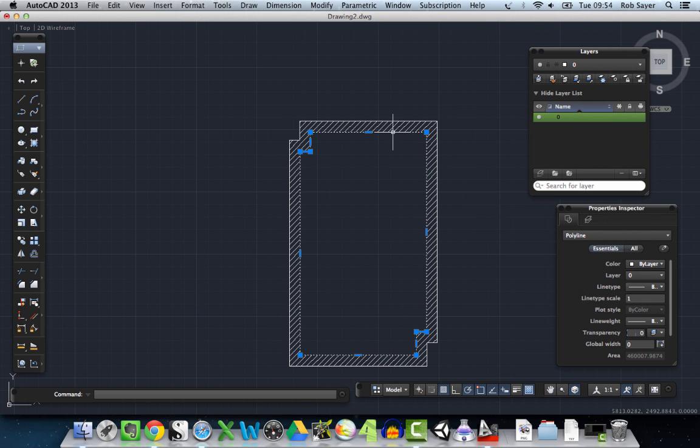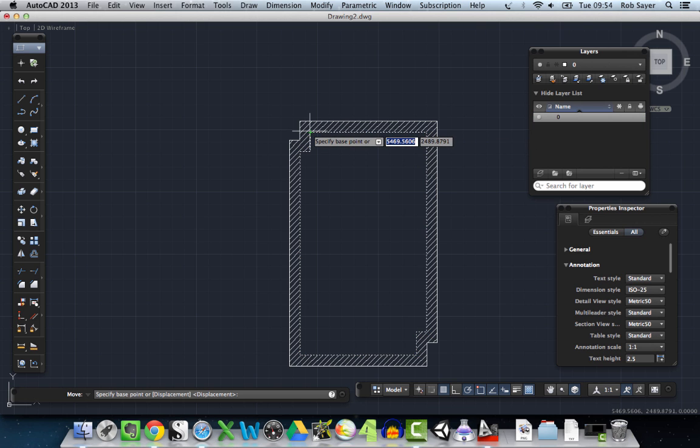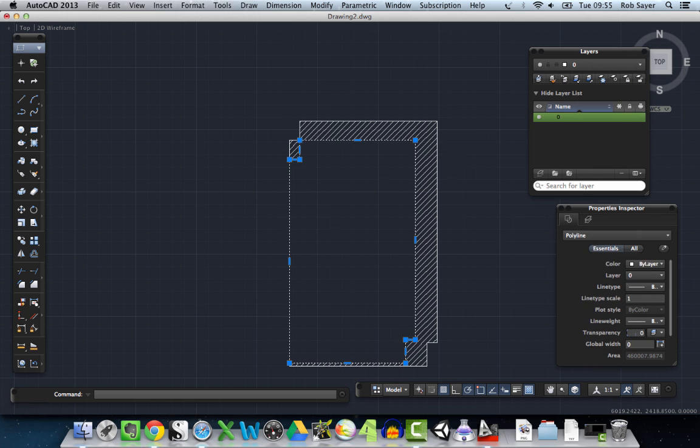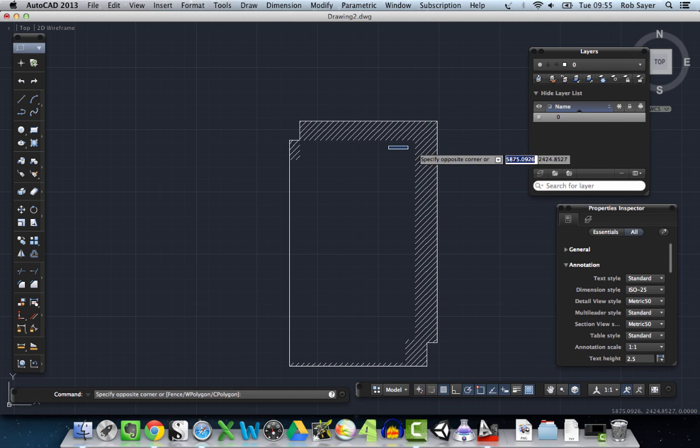You'll notice this particularly if I do a move. I can just move the inside shape a touch, and you can see that it's changed the hatch to fill the gaps. So the hatch is kind of spreading out like water in between the two shapes. If I delete the top shape, you can see what's happened there is it's basically left the hatch as it was, but the shape has gone. So the water now hasn't spread.